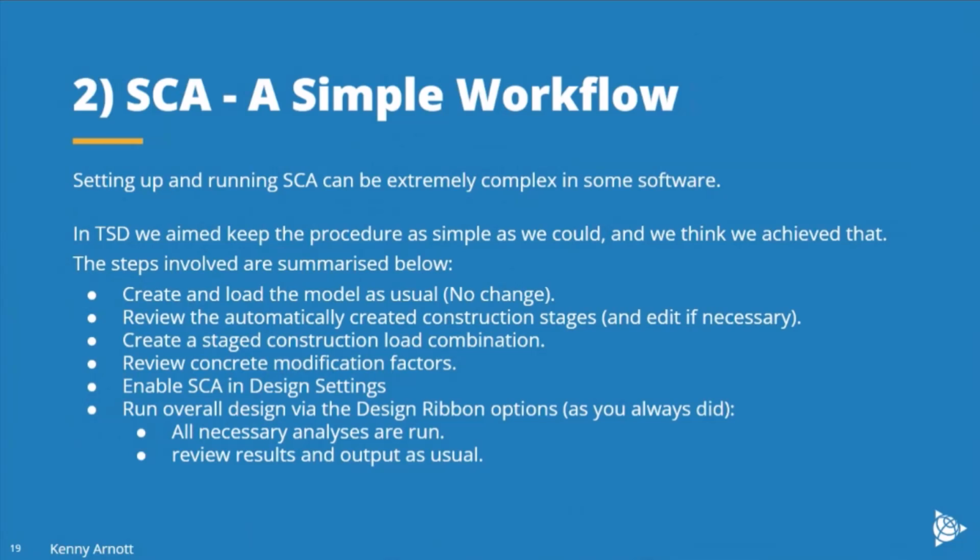We've got in here something about reviewing concrete modification factors. That's more for awareness than anything, but again, we'll go into that in detail in one of the later webinars. Then you need to enable the stage construction analysis to indicate that you want it to be used for design. And then you just run the overall analysis and design process in the same way as you always did. And TSD will run all the necessary analyses and then run the design considering the results of stage construction analysis.